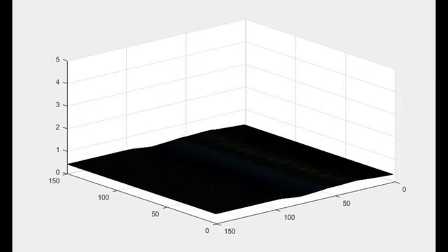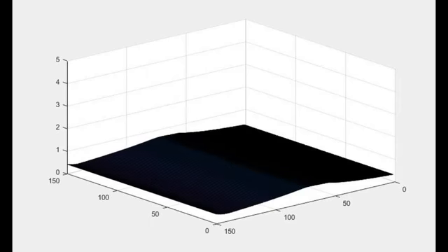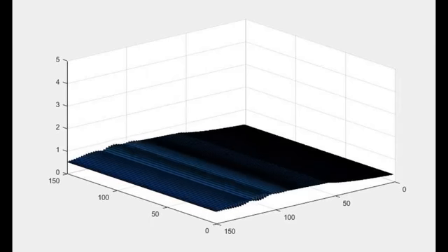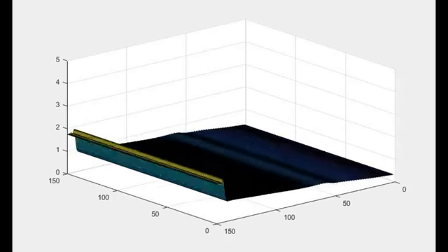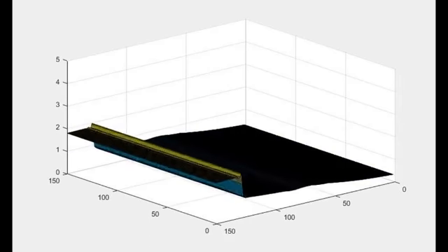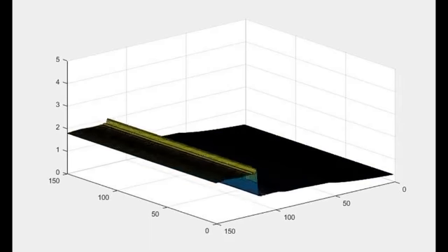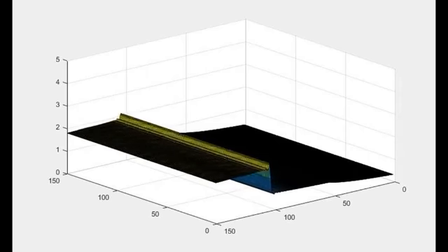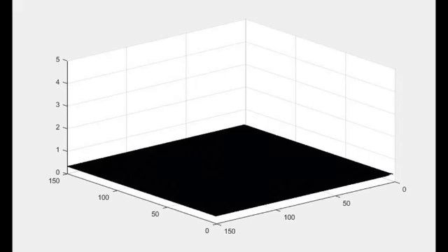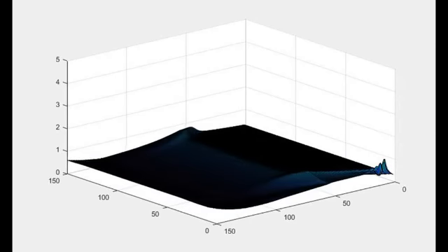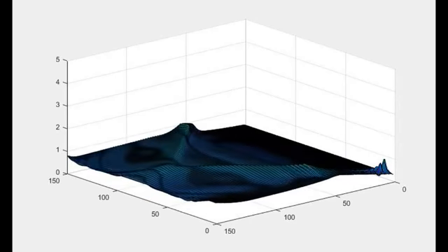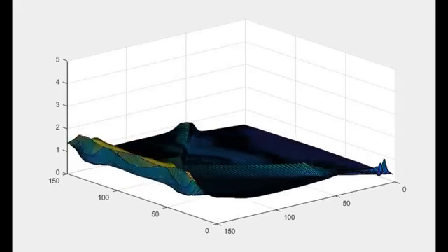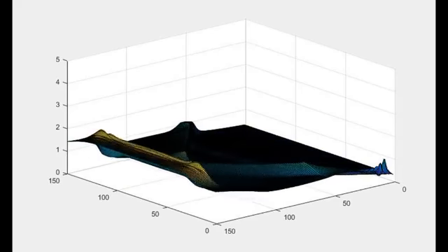This video shows the solution of free flow boundaries. The wave forms relatively quickly and moves back until it stabilizes near where the u gradient is. The following video is the solution with the no-slip boundary conditions. The wave once again forms and is much smoother, but there are artifacts that occur where the v and u boundary conditions interact.